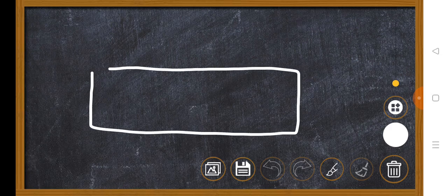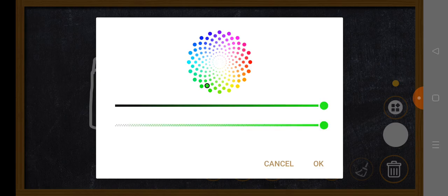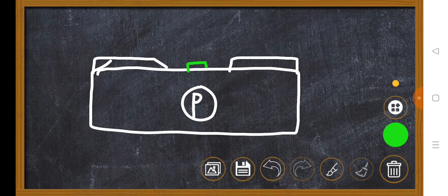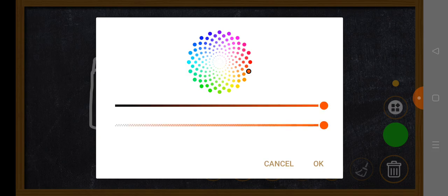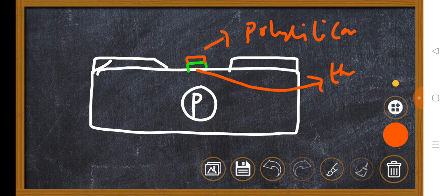Let us consider this is your p substrate. This is your, absolutely, what is that? Oxide, thick oxide, and you require here a gate oxide in this place. This is your gate oxide. On that gate oxide, what is present? Absolutely, polysilicon is present. That means you can call this the gate. Is it understood? This is your polysilicon, and what is this one? Absolutely, this is your thin oxide. I hope you are clear. This is your what? Thick oxide. Is it understood?